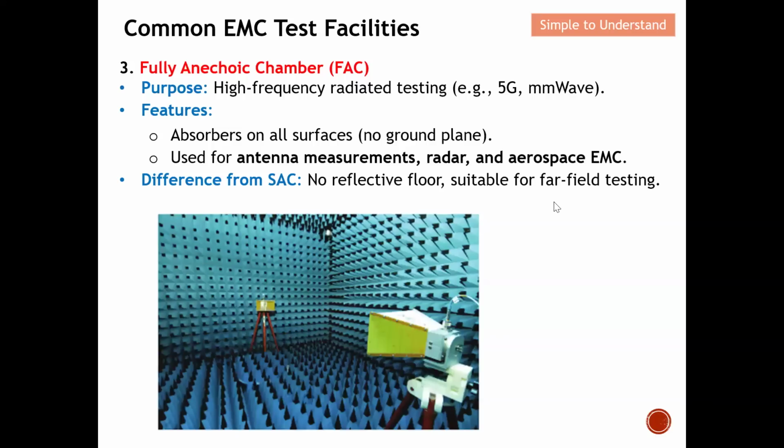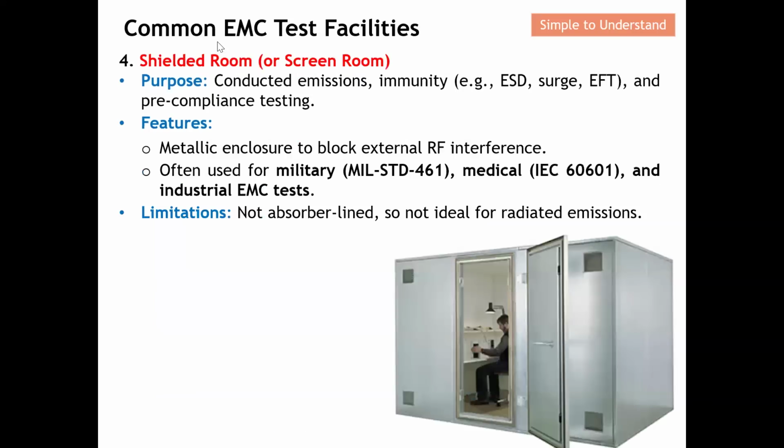So basically, in general, nowadays in EMC testing, if we want to go from low frequency to high frequency, you probably need to lay the absorber on the floor so as to move on to the higher frequency. So in short, the semi-anechoic chamber may still exist for lower frequency, but fully anechoic chambers are mainly targeted for high frequency testing.